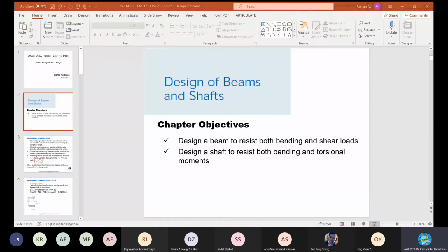A bending design requires the beam section modulus, right? I over c is S. Hence, using the flexure formula, sigma is equal to My over I. Later, I will change the notations. It is My over I. We can have the formula as section modulus equal to M over sigma. M max is determined from the moment diagram, and sigma allowable is specified in a design code.